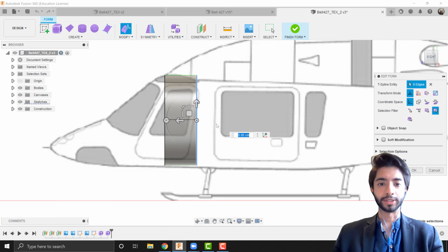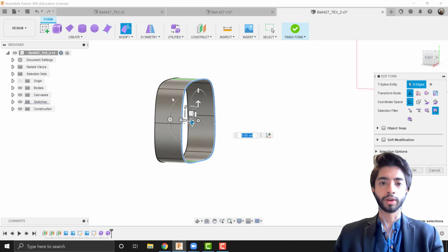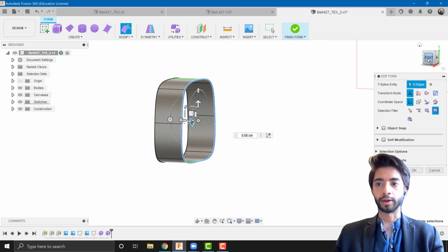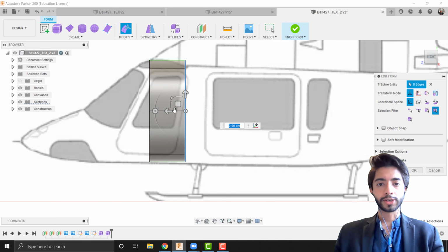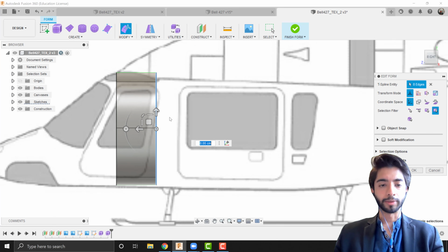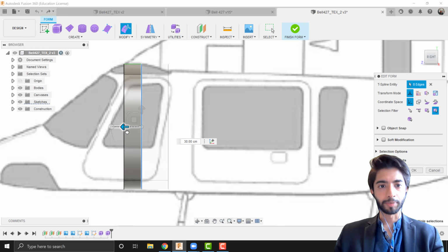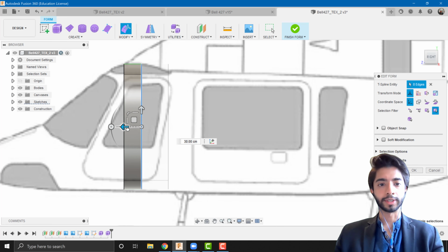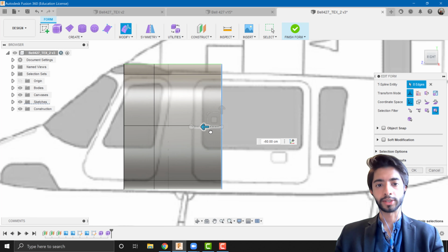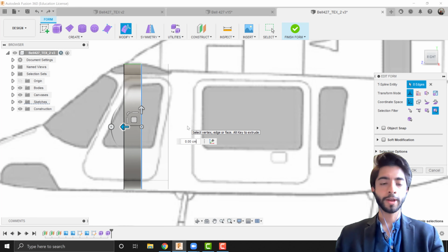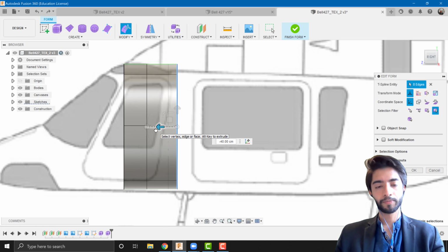What this does is it selects the entire ring on the back edge and allows us to edit it. So once you've done this, I am just going to follow that. I'm going to shrink this a little bit. Actually, let me bring it back a bit so it's more clear. Then I'm going to press Alt on my keyboard, and what Alt does is it allows me to extrude it. You'll see that it's created a new section instead of just pulling the previous one along. So Alt and drag. Great.